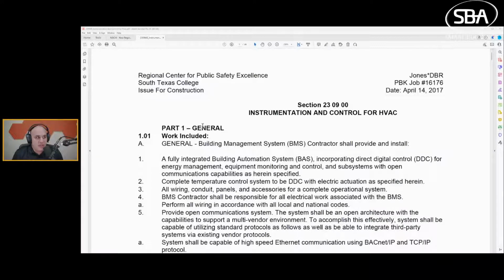And then we have our 0 to 10 volt DC outputs. This is typically for proportional things like actuators, speed drives, etc. And we have our 4 to 20 milliamp output. That's our current output, and that is typically used for the same stuff.